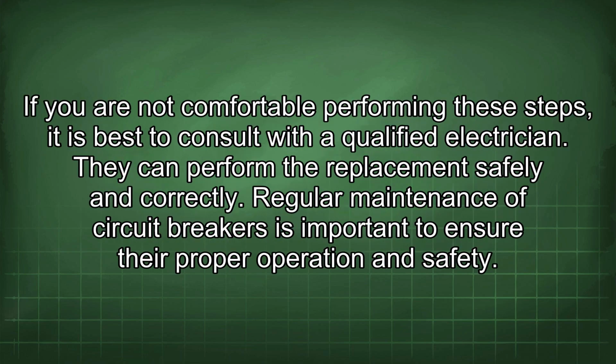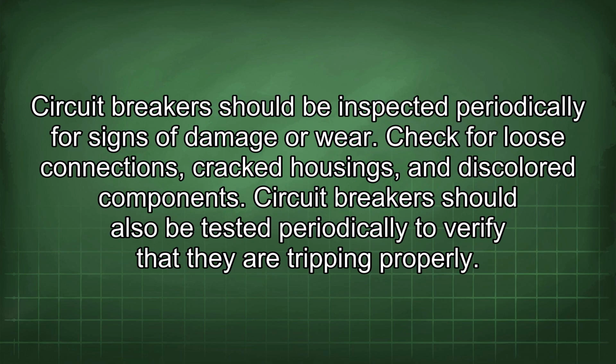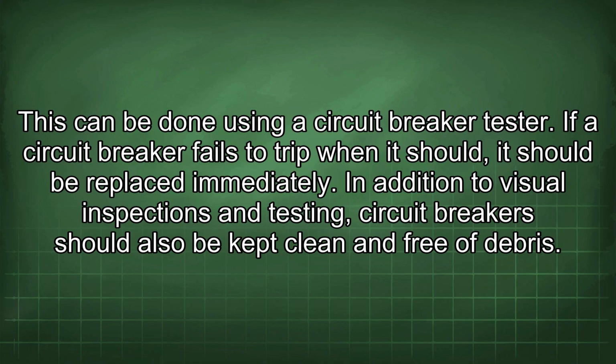If you are not comfortable performing these steps, it is best to consult with a qualified electrician. They can perform the replacement safely and correctly. Regular maintenance of circuit breakers is important to ensure their proper operation and safety. Circuit breakers should be inspected periodically for signs of damage or wear. Check for loose connections, cracked housings, and discolored components. Circuit breakers should also be tested periodically to verify that they are tripping properly. This can be done using a circuit breaker tester. If a circuit breaker fails to trip when it should, it should be replaced immediately.